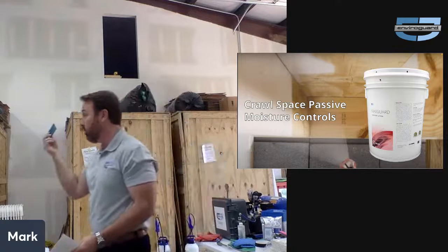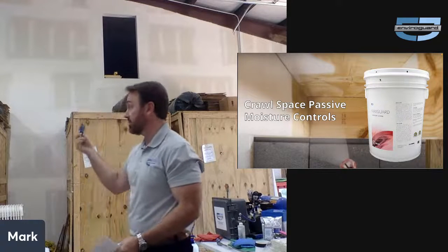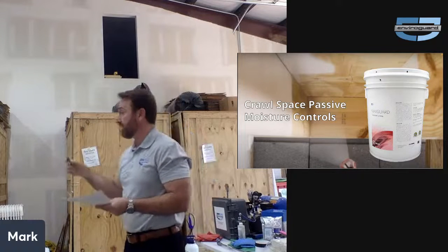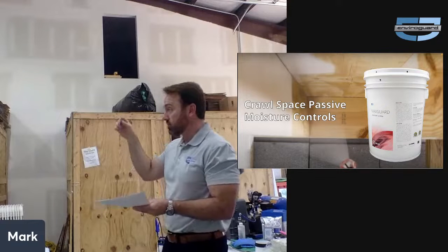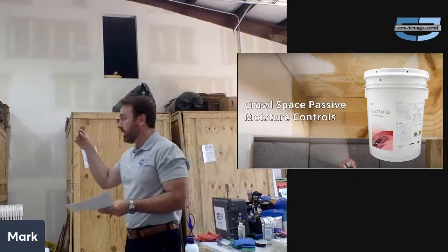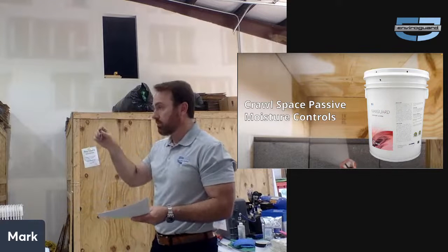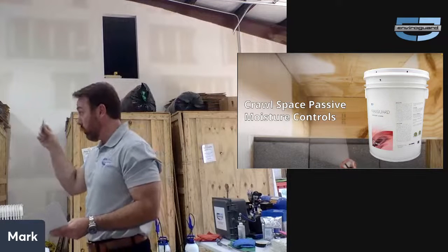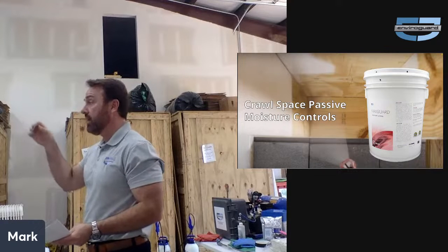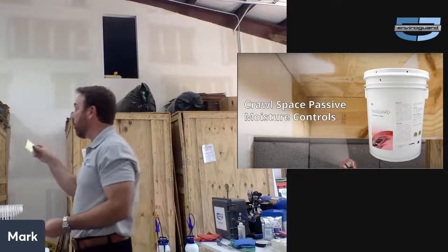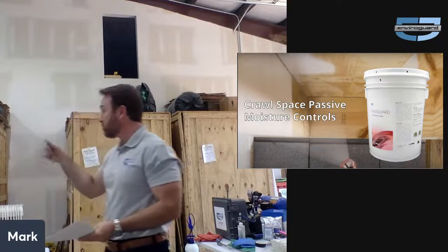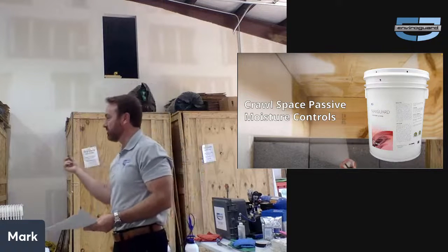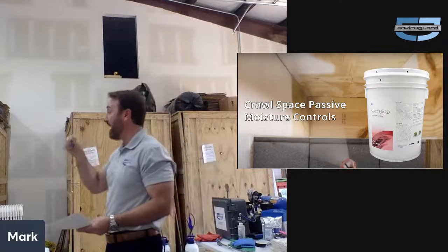Otherwise, how do you know that your product's going to work, right? Is it going to work at 1 wet mil the same as it does at 10, the same as it does at 20? Who knows, right? But if you follow the manufacturer's specifications to the wet millage, 20 wet mils is equivalent to 80 square feet per gallon. The standard number to get to how many square feet per gallon, if you know the wet millage, is 1,600. So 1,600 divided by 20 is 80. That tells you it's 80 square feet per gallon. Ours is 10 wet mils. 1,600 divided by 10 is 160, which is 800 square feet per 5-gallon pail.